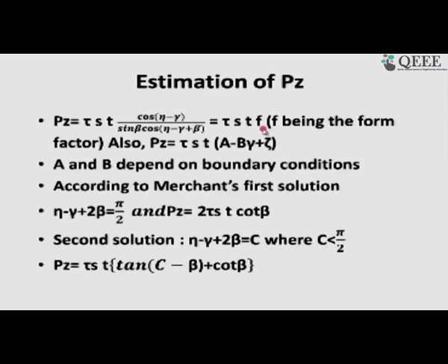It is quite a significant work that without any experimentation, if you know the shear strength of the material, if you know feed and depth of cut, and knowing the value of F from the shear angle and a relationship, it should be possible to estimate the cutting force without even having a dynamometer.